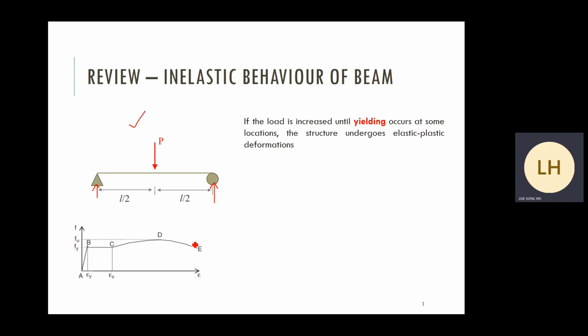In the past, we assumed that the material remained elastic. Elastic means no yielding occurred. What is yielding? You may take a look at the stress strain profile at the bottom. At the left-hand corner, I showed you a stress strain profile for materials. In the past, we considered the AB region. Material remains elastic, so you can apply Hooke's law when you're considering these elastic regions. But you can see that beyond a certain level, beyond point B, materials start to enter another status. We call that yielding.